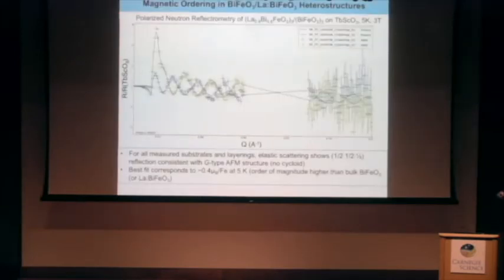So this is one of our films. This is a 3-repeat film now. And I should note that the TEM of this film shows that we get an anti-ferroelectric pattern throughout the entire film, which maybe is unsurprising because there should be some crossover regime where they're coupled. And this is actually a composition that is in the morphotropic phase boundary, despite still seeing clear segregation where the bismuth ferrite is bismuth ferrite and the lanthanum ferrite is lanthanum ferrite. But if you average over the whole system, you're in the morphotropic phase boundary, which is kind of what's always going to happen for these 40% lanthanum films with 50-50 superlattice ordering.